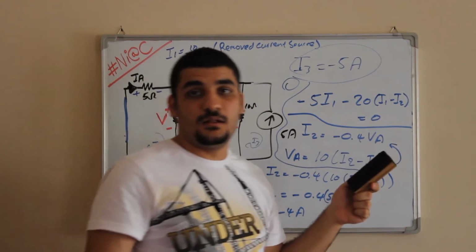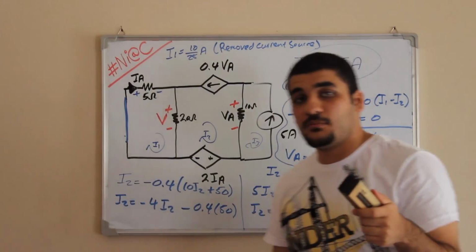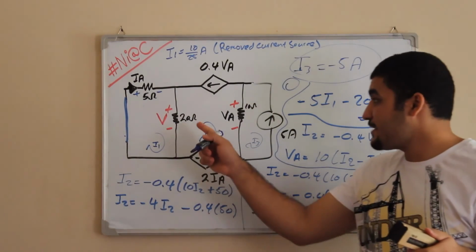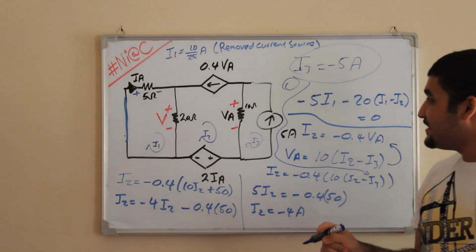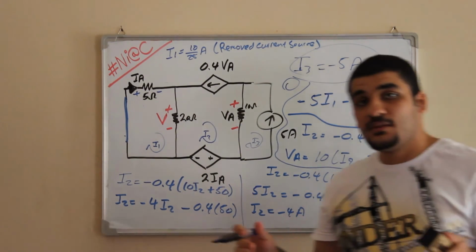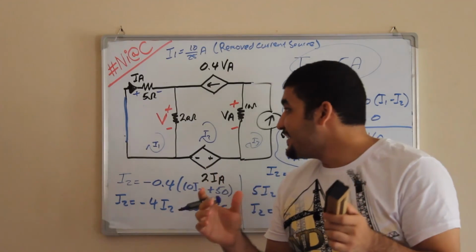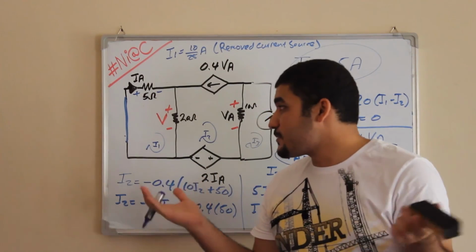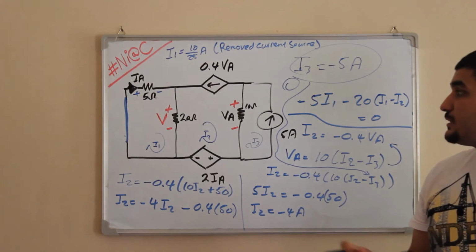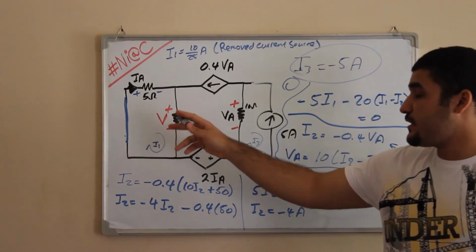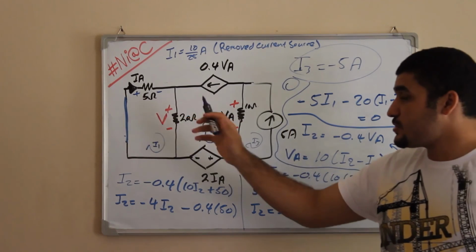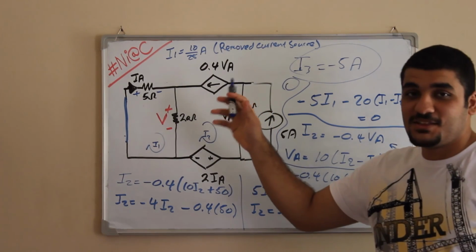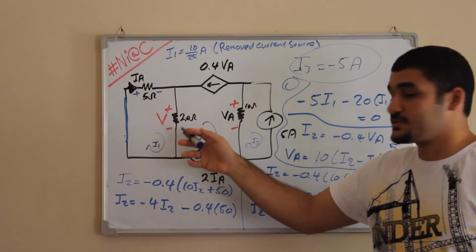After finding the voltage across the 20 ohm resistor, you sum the two results together, which is the superposition. The final voltage is the effect of the two sources on this 20 ohm resistor.